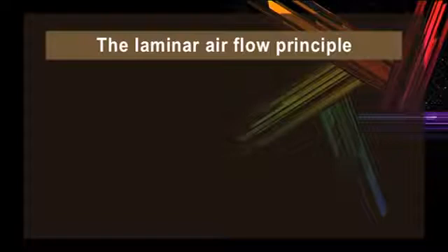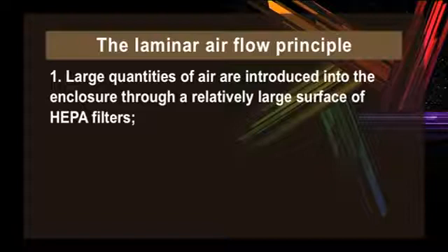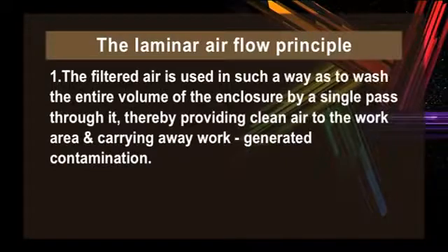Satisfactory application of the laminar airflow principle to produce a clean environment depends upon two rather simple features. One, large quantities of air are introduced into the enclosure through a relatively large surface of HEPA filters, and two, the filtered air is used in such a way as to wash the entire volume of the enclosure by a single pass through it, thereby providing clean air to the work area and carrying away work generated contamination.